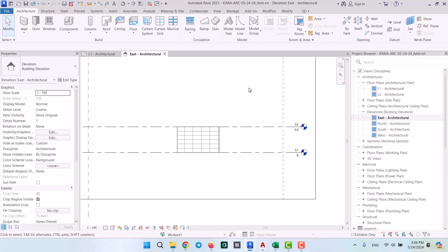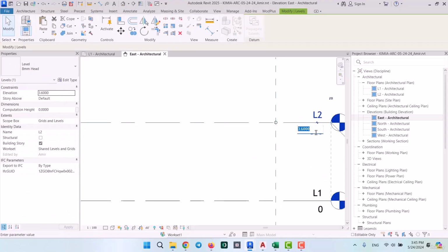Now you are thinking, right, but it's still not very accurate to do. So despite all of that, it's still not the most accurate way. Now why is that? Once again, it's because of the alteration process. You see, if the offsets of your structural levels are required to change for installation and structural reasons, then what should you do? You would have to first go over to your structural plan and change the level offsets there, and then you'll have to do that again in the architectural file as well. As in, you would have to change the offsets in 2 separate files.